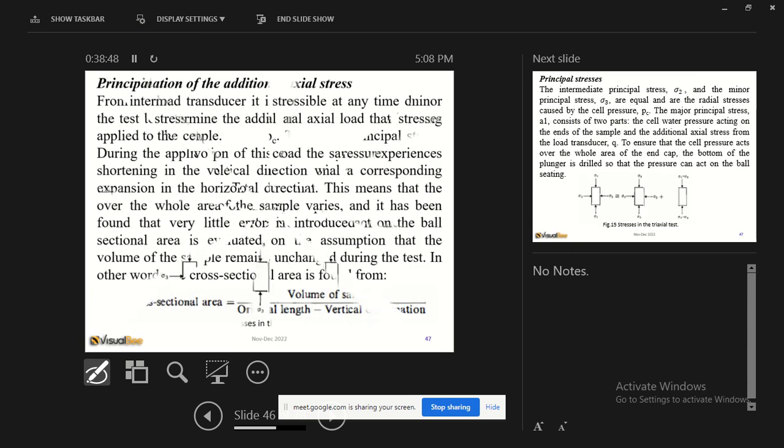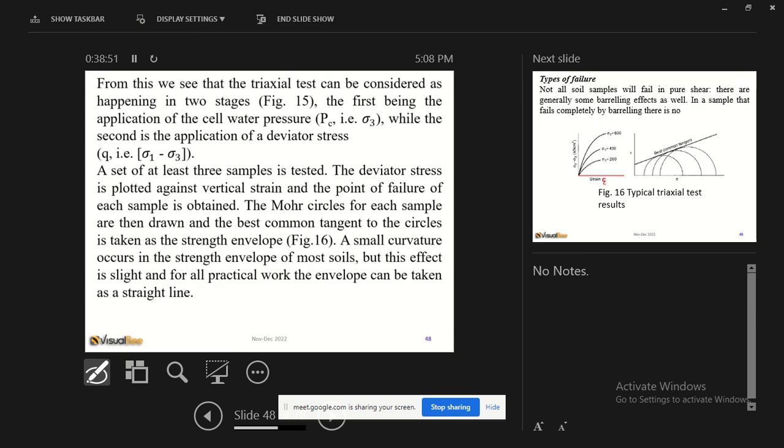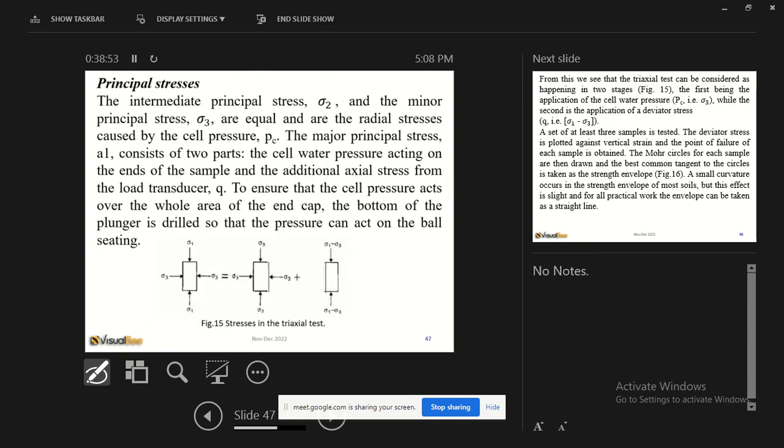So that's for the triaxial test. In the triaxial test, these are the principal stresses, if you remember. These are directly principal stresses, and here the shear stress is 0, and sigma 3, again, shear stress is 0. That's why you can afford to draw this.